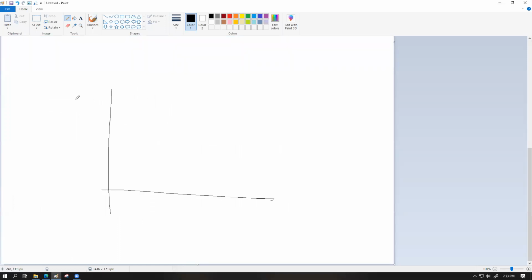The basic shape of the stress strain graph for metal is like this. Stress strain graph, we have a perfect straight line part, then we're going to have a UTS point, this is going to be identical, and then from this point it's going to have different breaking behavior for specimens which are drawn from the same part. So we're going to have a drop from here, and it can break down at different locations. These cross points represent the rupture point, and this is exactly where the necking gets started.